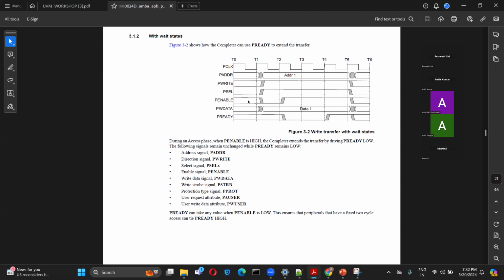So to increase the performance, you will go with AXI instead of APB, because in AXI within less time you can send more 32-bit data. If through APB I am sharing two 32-bit data in some time, within the same time through AXI I can perform 5 to 10 data transfers. So if performance is your main constraint, then you will choose AXI.